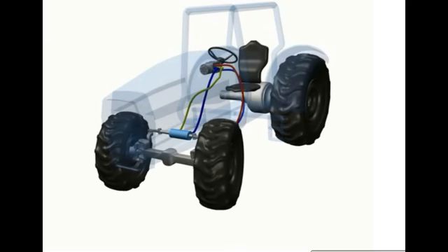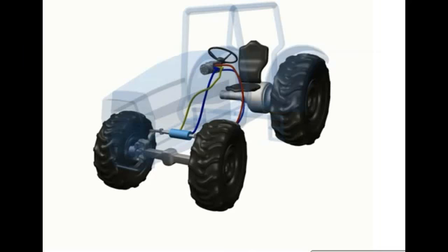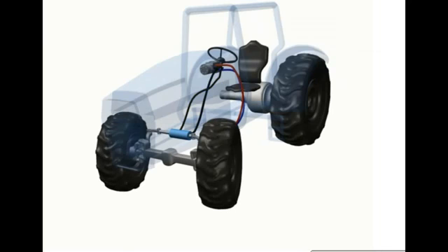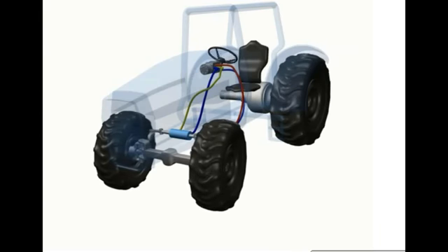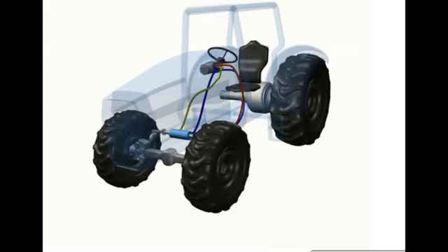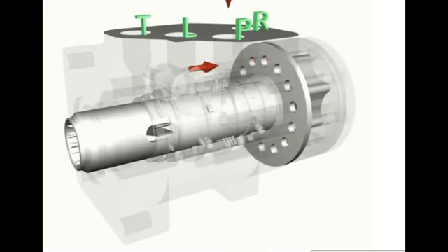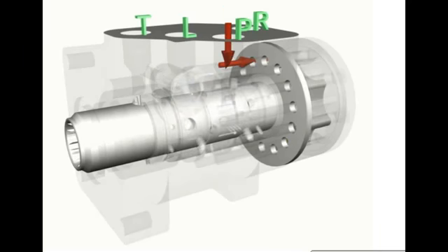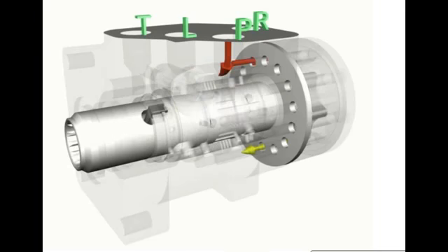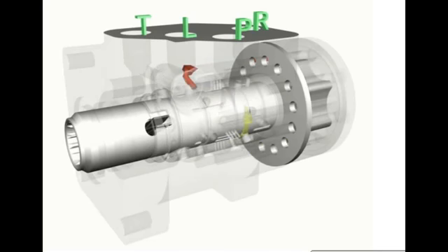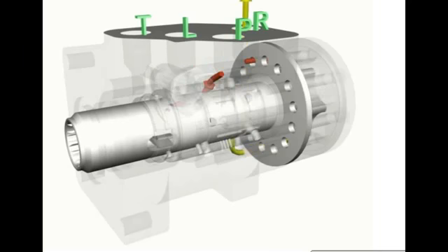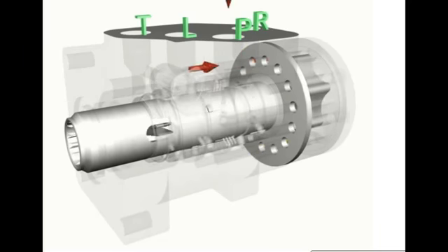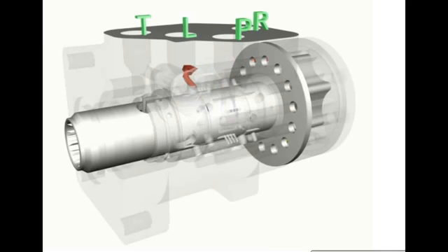Pump flow not used in the steering circuit passes through the tank port of the unit to the reservoir and to other downstream functions through the power beyond port of the unit if provisions are made for this option.